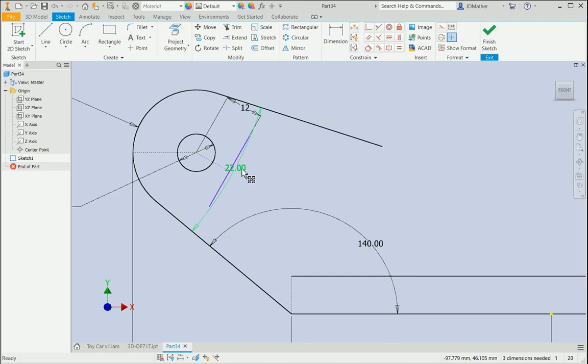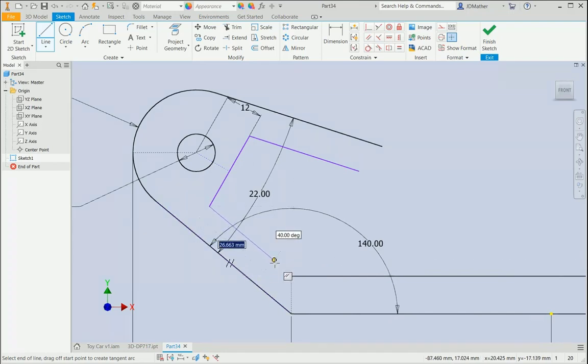and I will then put in a line along here, and I want this line parallel to that line, so I'll scrub that line, and there's the parallel, and I'll do the same thing on the other side. So I'm going to do a line on here, and I'm going to do it parallel to that line. Now I put this line to the midpoint of that one, and I'm not really sure that's where it is at, but we'll find out here in a few minutes.